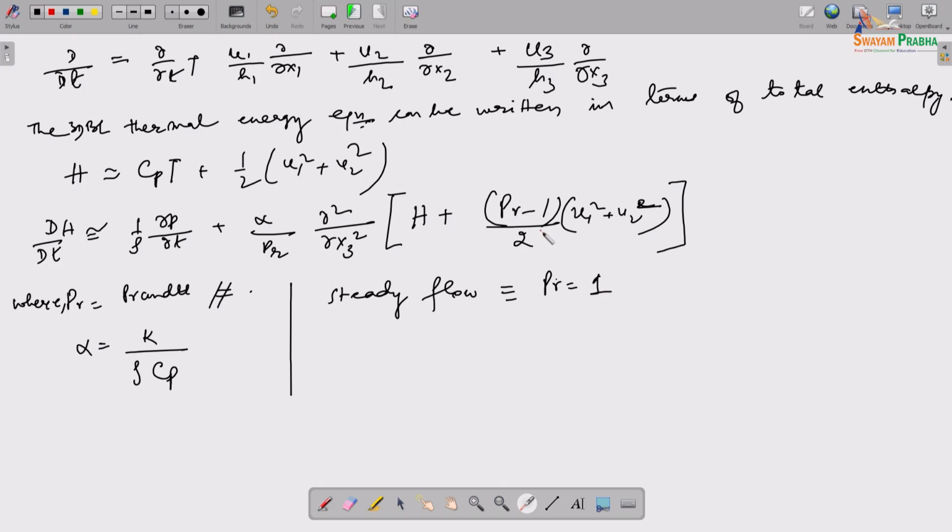So what we are left with should tell us that the total enthalpy H is constant everywhere, if the boundary wall is insulated. That is, Crocco's relation is not affected by three dimensionality. That's something to point out here.